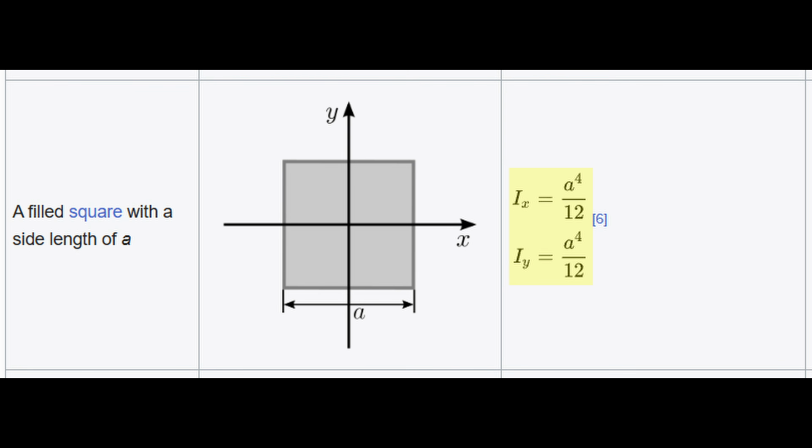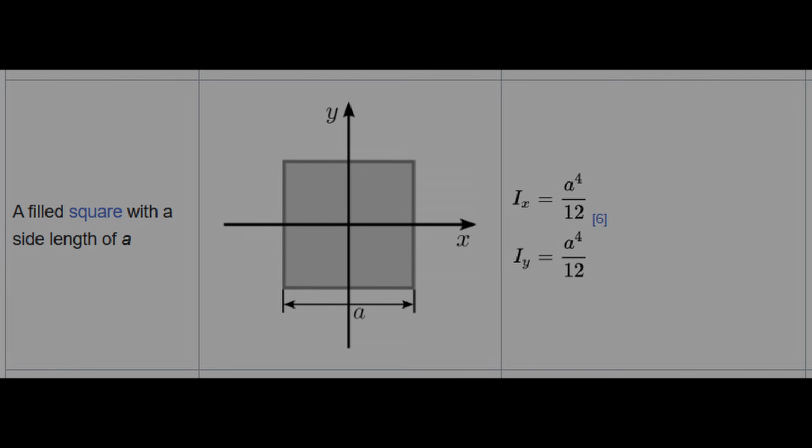If you recall, in the Euler formula, it's the minimum area moment of inertia that is used. That means for our tower legs, given a cross-sectional area budget, it's best to use a square shape so that the buckling strength will be the same in both directions.